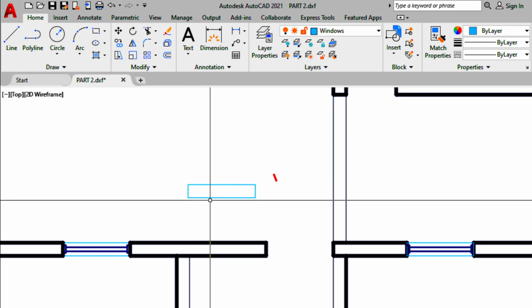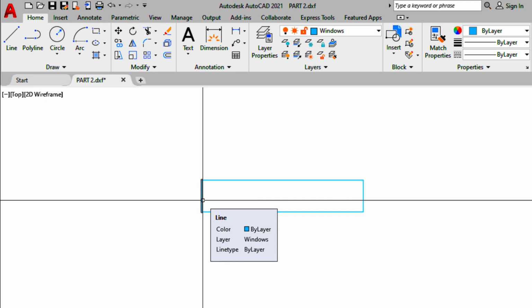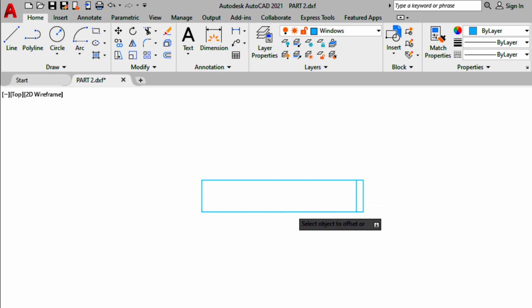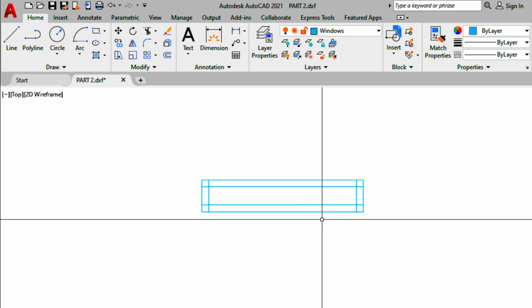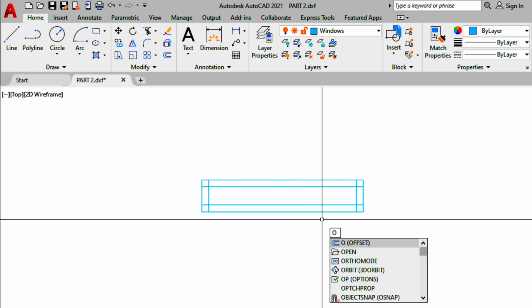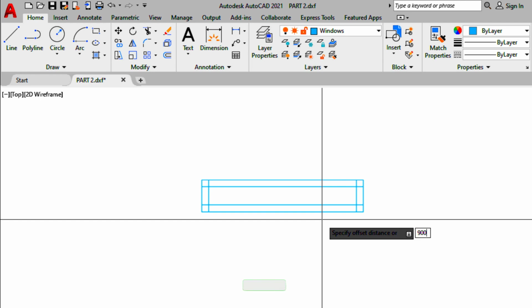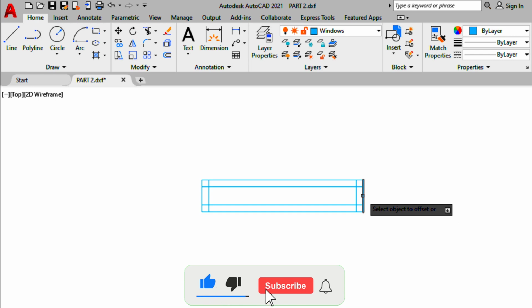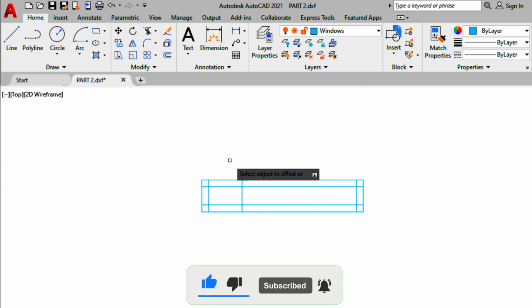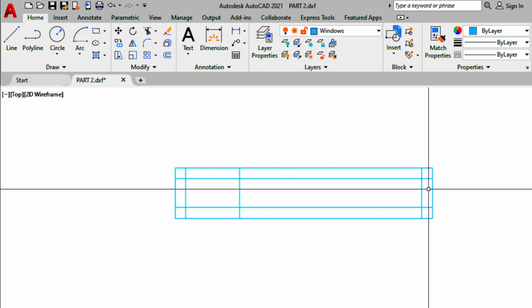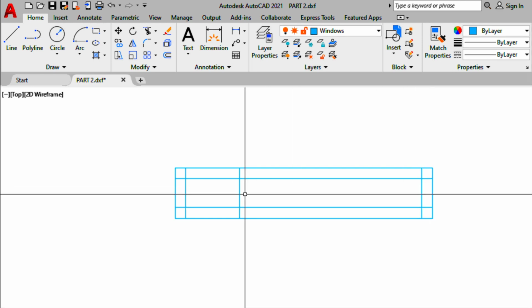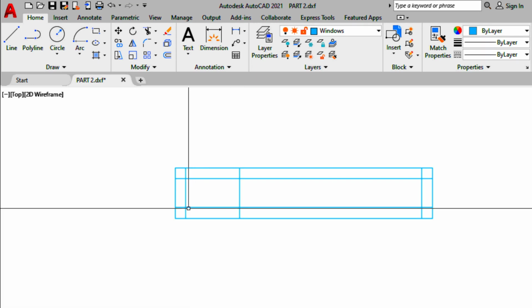I want to create a double swing door here because it's the main entrance door to this building. Now what I'm going to do next is to offset 50mm. I'll type 50mm and press enter and offset 50 all round, and press escape after I'm done. Now I'm going to offset 900mm again. I'll type O on my keyboard and press enter to activate the offset command, and then type 900mm and press enter on my computer keyboard. And I now offset 900mm inward. The first leaf of my door is starting from here to here, that's 900mm, while the smaller leaf would swing from this line to this line.